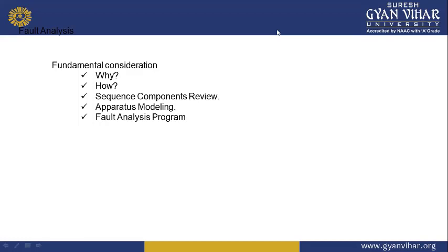It is very important to note that the majority of the system faults are not three-phase faults, but faults involving one line to ground or occasionally two line to ground faults. These are unsymmetrical faults requiring special tools like symmetrical components and form the subject of study of the next upcoming slides and sessions.